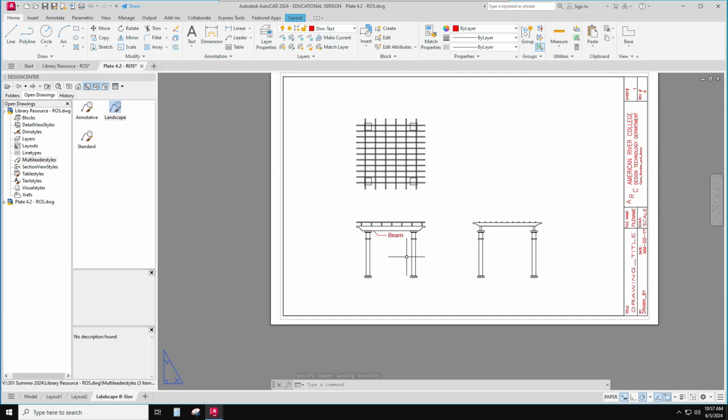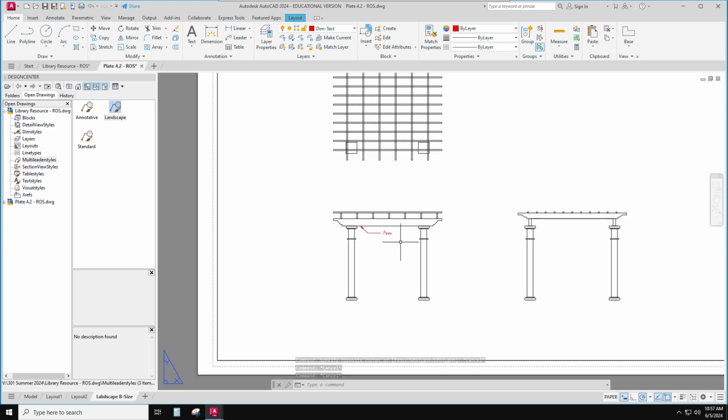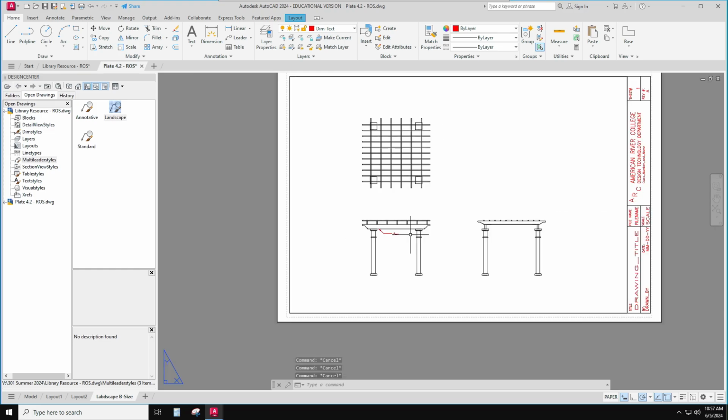And let's make sure that I put that on the right annotation one. I want it to be landscape. Oh, that's going to look much better, right? Looks like everything's going to fit much better. So make sure that your annotations are set to be landscape, and make those changes like I did. And then you can go back and put all your stuff on there.